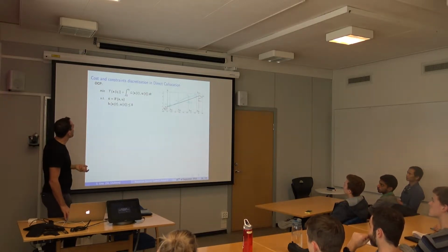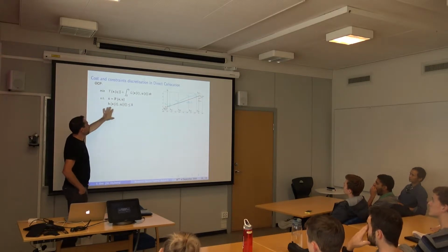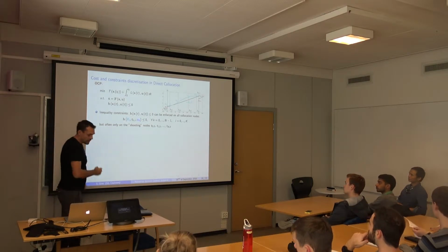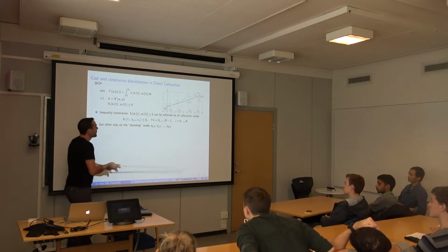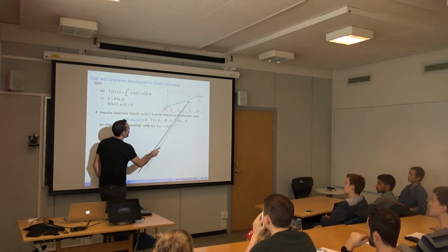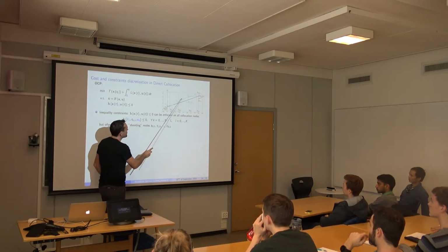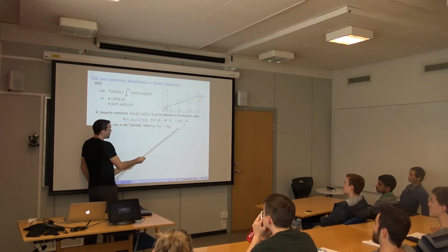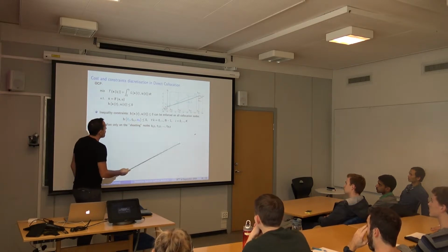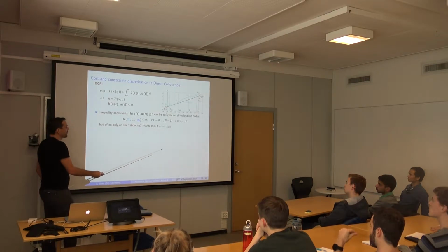Maybe a few words on the details of how you discretize OCPs with direct allocation. So again, that's the starting point, your OCP, possibly with some boundary conditions and other kinds of constraints. So concerning the inequality constraints, now since you have more states inside your NLP, not only the xk's but also all the states in between, in principle you can impose your inequality constraints on every one of your points in the time grid. In theory, you could even calculate the trajectories on any point you want using the polynomial interpolation and put the inequality constraints on them as well. So in that sense, you can impose the constraints as densely as you want without doing anything special in your formulation. However, it's quite common to impose them only on the main tk, so the main time grid. It's often sufficient to do that for practical purposes.